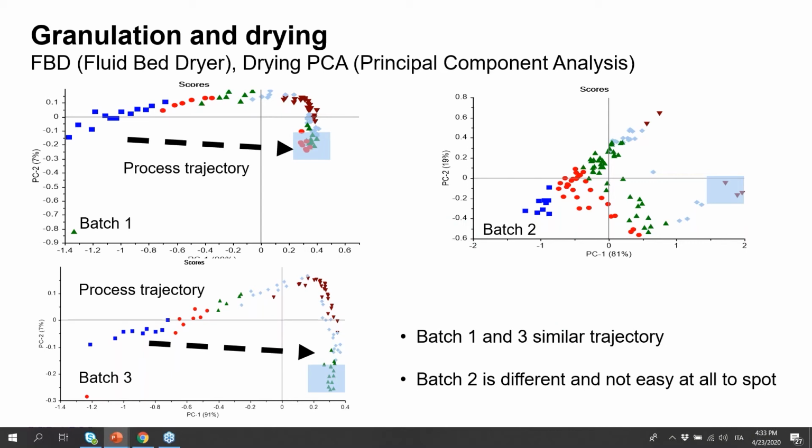It ended up that because it was very close to lunch time, they decided to make the granulation in the high-shear mixer a few minutes shorter, because the product, looking by eye, was somehow good, and probably the particle size was different.